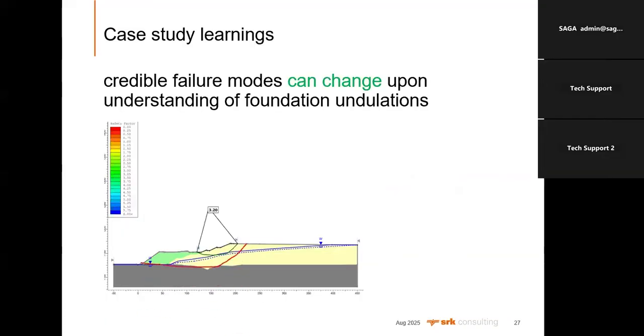The impact of this, if we as tailings engineers have a credible failure mode that goes through the foundation, you cannot believe the ramifications that has on environmental considerations, emergency planning, liability, insurance, et cetera. So if we depict the foundation, for example, in igneous rock with straight lines, and we have a credible failure mode that pops out like that, it has massive ramifications.